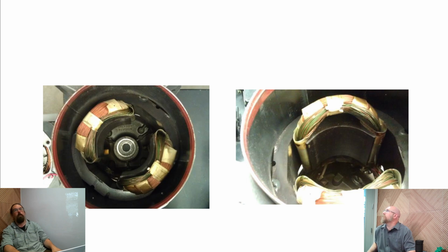When we energize this motor, one side of this set of coils is going to become your north pole, the other side will become your south pole, and then the brushes are going to create essentially the opposite. If you take a look at these two windings here, the brushes are coming in between them, so they're energizing coils that are in between the two of them.